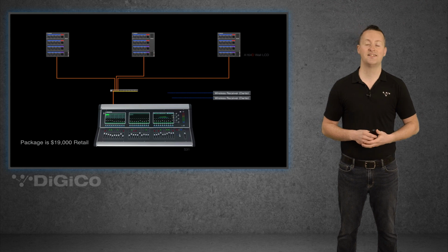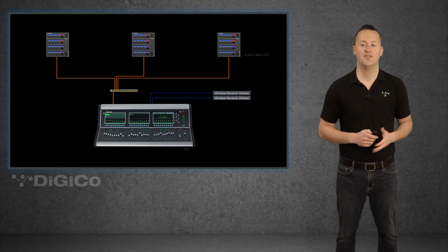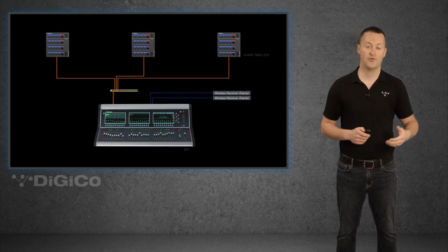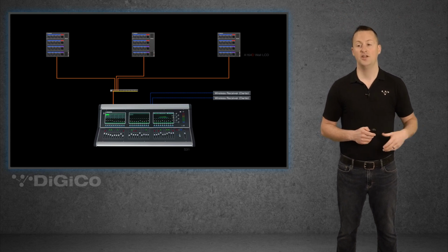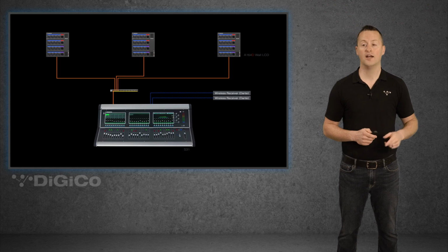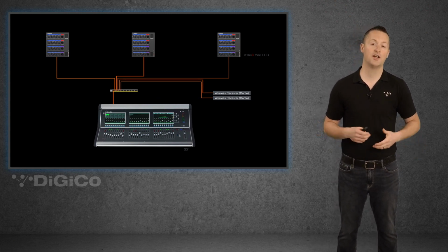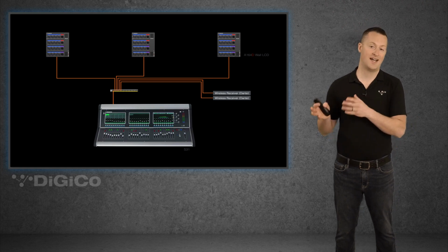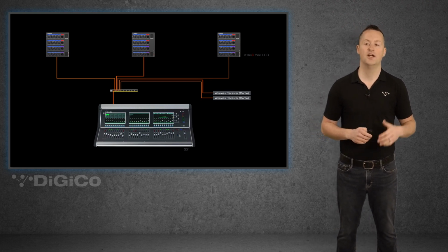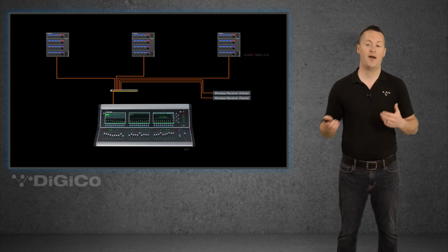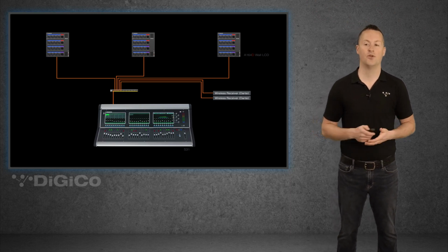All right, maybe you have existing wireless microphones already. These can simply be plugged into the mic pre's on the back of the console if they're already at front of house. If they're at the stage, you can plug them into stage boxes, or if they're Dante enabled, we can bring them to the same switch. So maybe as you upgrade your wireless microphones, these things can reside in a rack mount enclosure, connect to the same switch, and be routed through Dante software back to this console. Everything can be controlled through there.